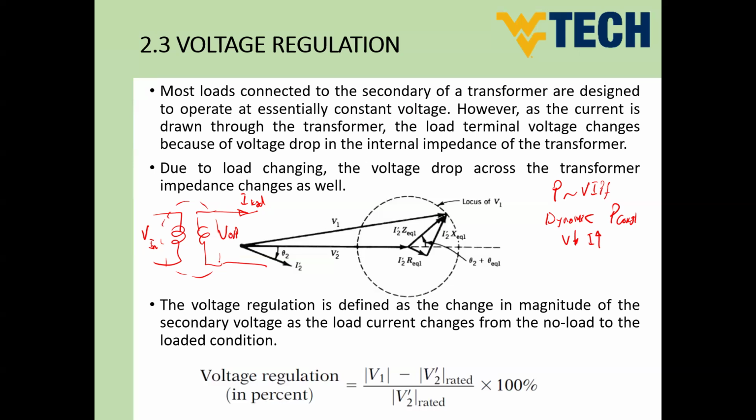So again, we can solve the constant voltage of the transformer in two ways: either by redesigning the transformer to have lower voltage regulation, or by having an external device to compensate the reactive power. By the way, such a device, guys, is referred to as power factor correction. This is on the low voltage side, or sometimes in substations we refer to what's called a static VAR compensator. The static VAR compensator provides reactive power in order to keep the voltage constant.